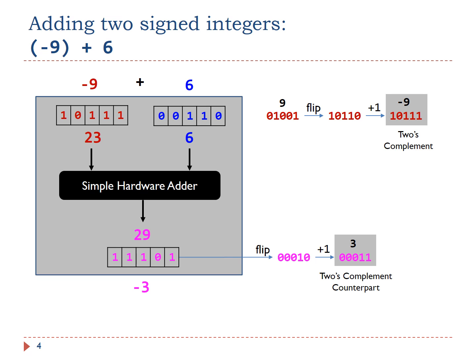This can be proved by inverting all the bits and adding 1. The result, -3, is exactly the sum of the original signed inputs. This example shows that, without any modification, the hardware adder designed for adding unsigned numbers works correctly for adding signed numbers.